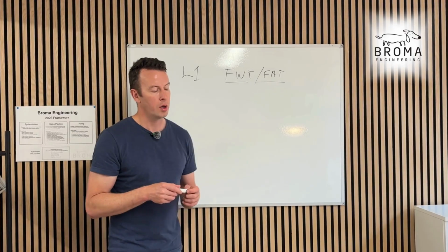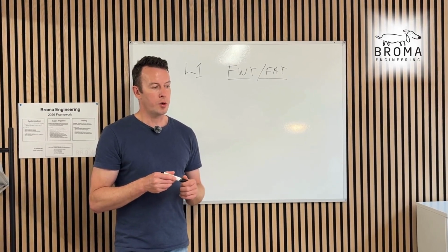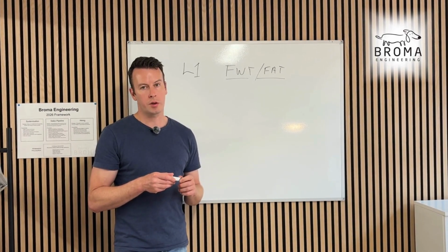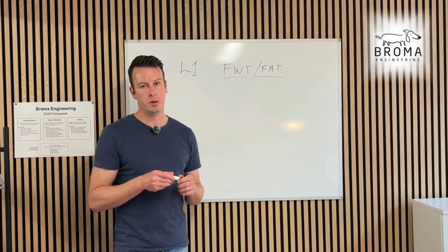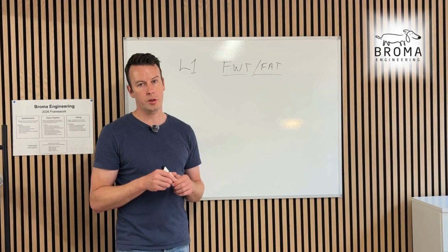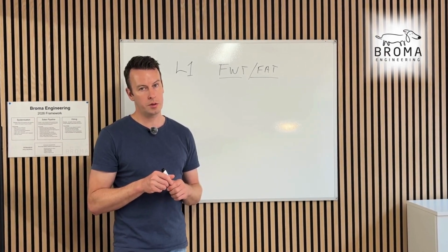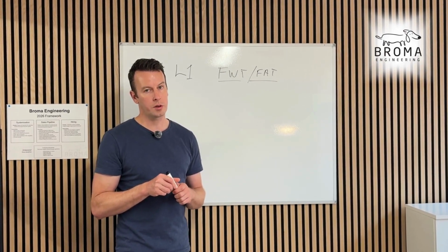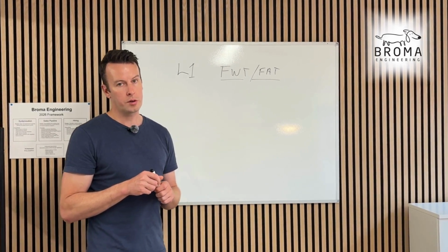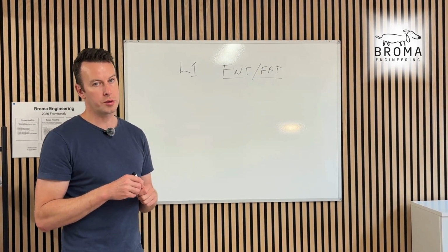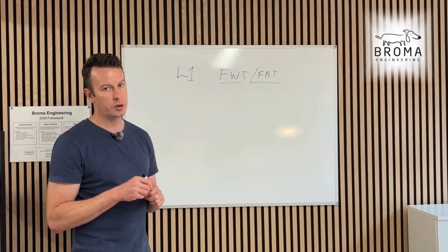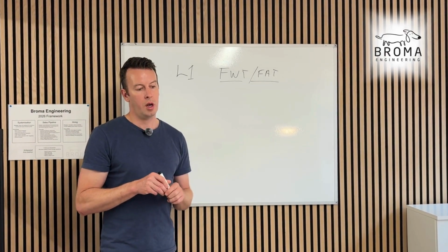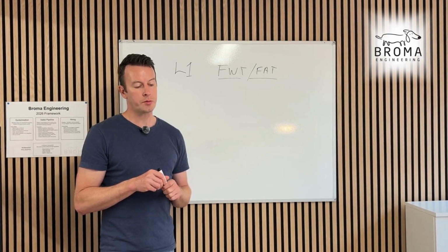So the owner of the building or the developer has already purchased these AHUs. You want to make sure that the technical submittal exists and it's approved, or if not, it needs to get approved. You need to understand who's going to approve it. So usually it's the design team and the engineers involved, whoever wrote the specification.